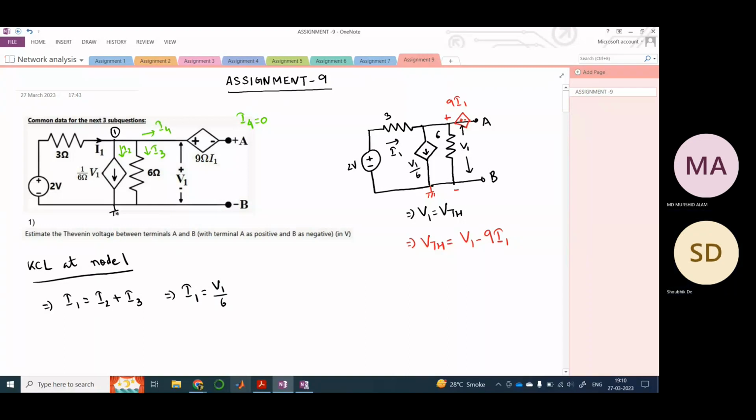Similarly in this voltage source also, it's current into your resistance, right? So I is the current and 9 ohm is the resistor. So it's actually 9I, and this is V1 by 6, nothing else. And similarly here also, this is the node voltage. So here this node and this node, the voltage is equal, so this would also be equal to V1 by 6. Therefore your I1 is V1 by 3.